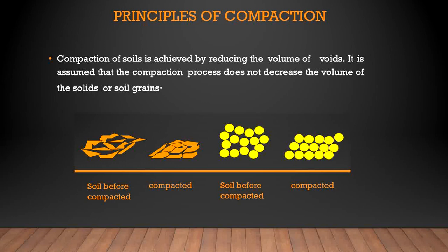The degree of compaction of a soil is characterized by its dry density, and the degree of compaction depends upon the moisture content, the amount of compactive effort or compactive energy expended, and the nature of the soil. A change in moisture content or compactive effort or compactive energy brings about a change in density. Therefore, for the compaction of a soil, a certain amount of water and a certain predetermined amount of rolling are necessary.